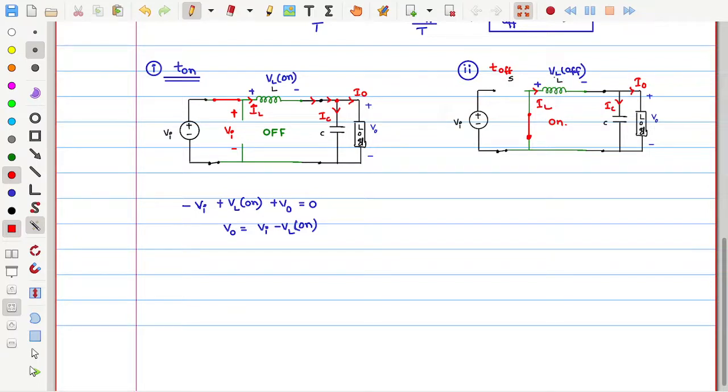By the property of the inductor, we cannot reverse the current, because current does not change suddenly in an inductor. So the voltage can change across this inductor. That means the polarity will become plus on this side, and minus on the left side. Then see, positive current is entering at the negative terminal, so it tries to supply the energy which was stored in the previous cycle.